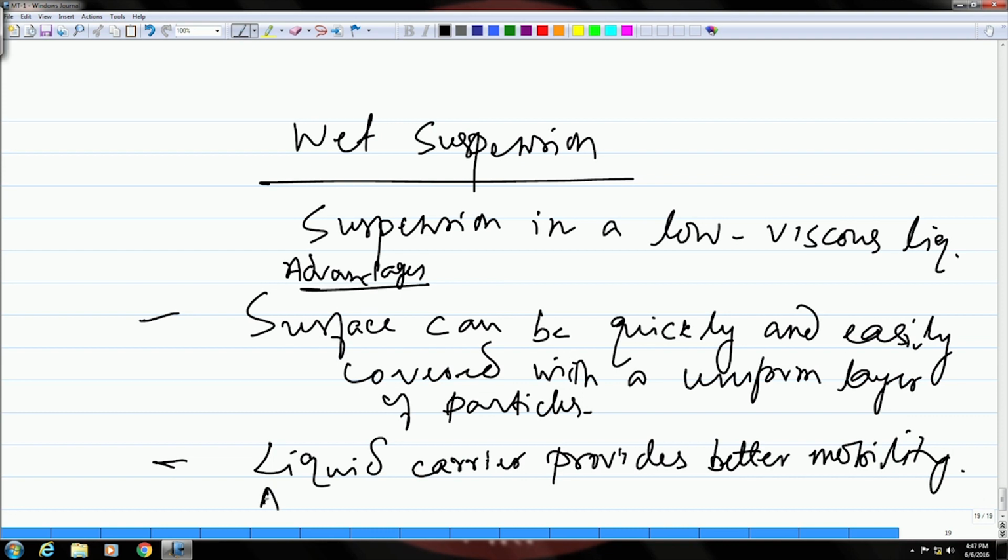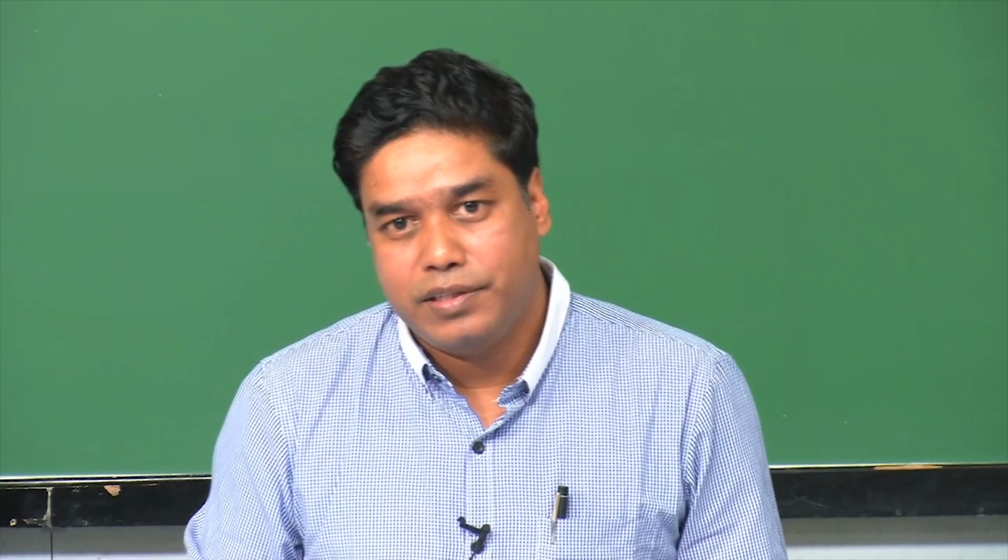And as a result enough particles can float to small leakage fields. Okay, because it is important not to miss the smaller defects; if the defect is very small, there is a chance that you might miss them.